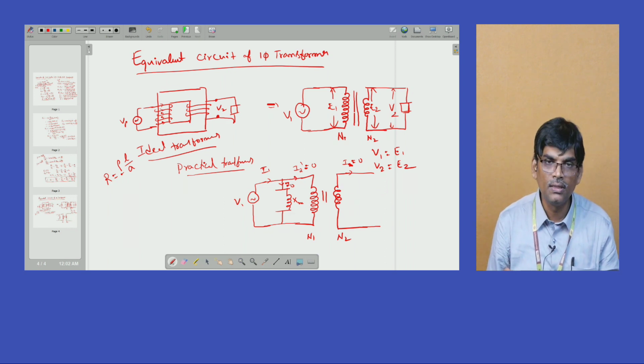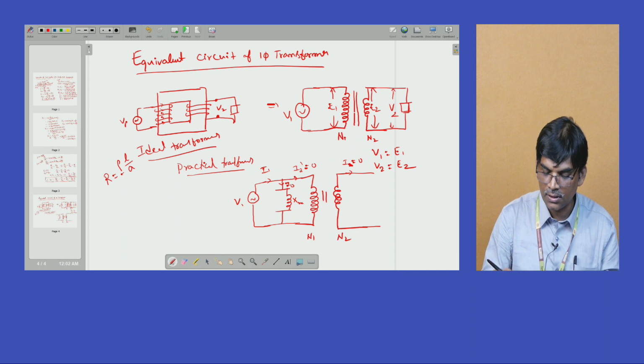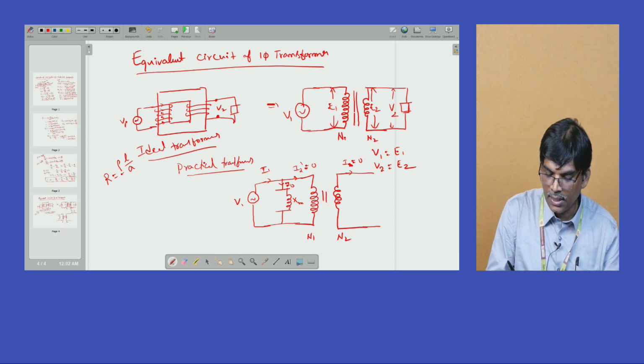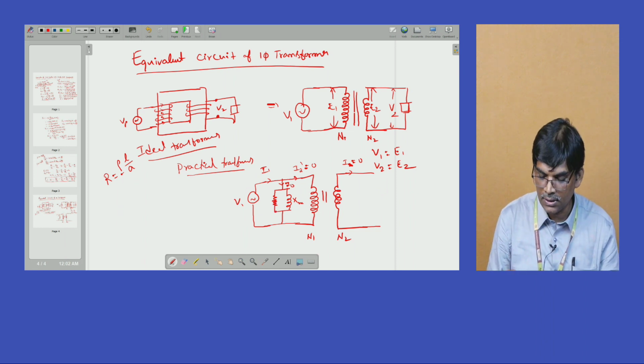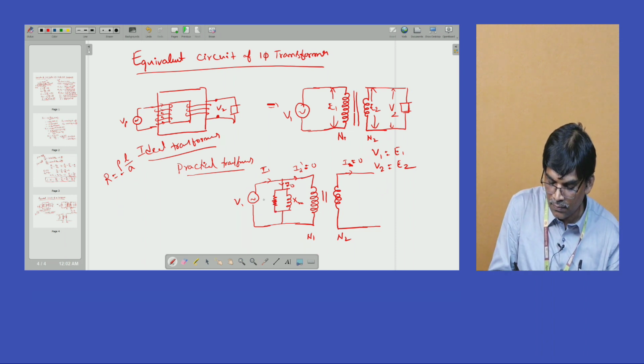only voltage. Why? Because of the flux reversal it is developed, and frequency is constant. In terms of the remaining voltage, it is already constant. That's why iron loss is treated as constant. The constant parameters we can represent in shunt. That's why, as this is a loss component, we can represent the circuit in the resistive mode. That's why this is called the working component.